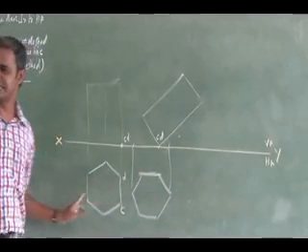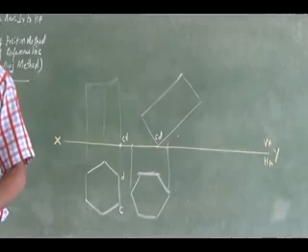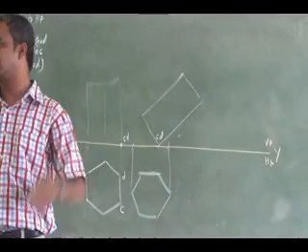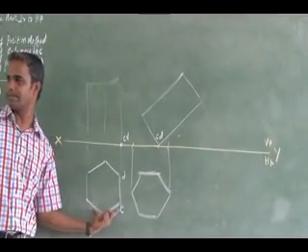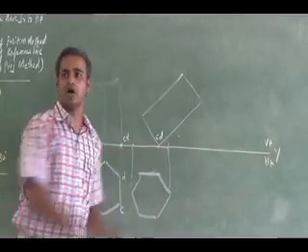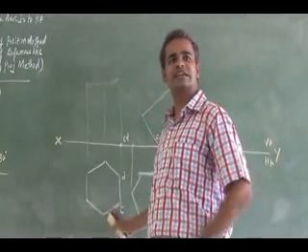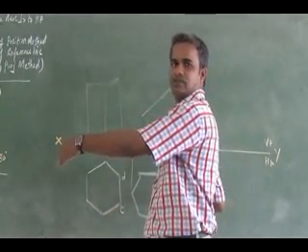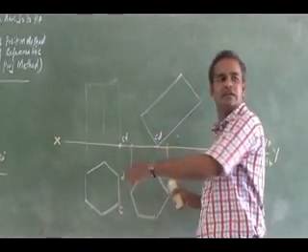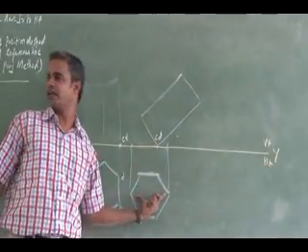As far as the hexagon is concerned, if it is resting with the edge, you draw the true shape of the hexagon in such a way that edges are in the extreme. So here I have edges in the extreme. Here you see what I have in the extreme: corner. If it is resting with the edge, you draw the hexagon such that the edges will be in the extremes. If it is resting with the corner, you draw the hexagon such that you keep the corners in the extreme. Is it clear?